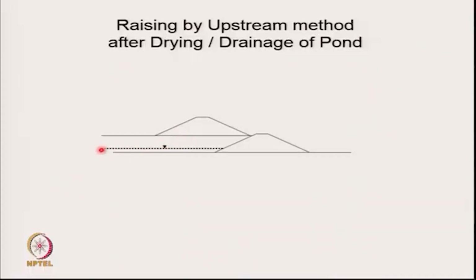Still, after 6 months when you came, what we would normally observe is that the slurry water level inside the ash would have gone down, and this ash, or this tailings, would either be moist or dry. When this becomes moist or dry, light earth moving equipment can move over this. So it is possible for you to make the embankment. If the water level is high, then even you can't stand, and even earth moving equipment can't stand if the water level is near the surface. So this is the standard method for raising this by the upstream method.